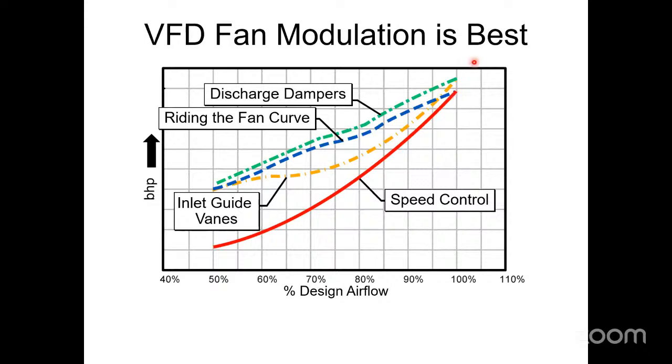So that's on the fan side. I mentioned you need to have VFD fan control based on a pressure sensor in the duct in order to have a VAV system with zone dampers on it. The other thing I said you needed to do, different than a constant volume unit, is you need to have capacity control of the compressor. You need to have modulating chilled water valves, you need to have an inverter-driven compressor, or you need to have multiple stages of fixed-speed compressors.